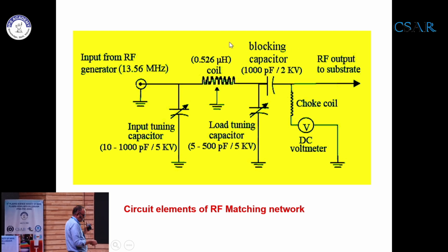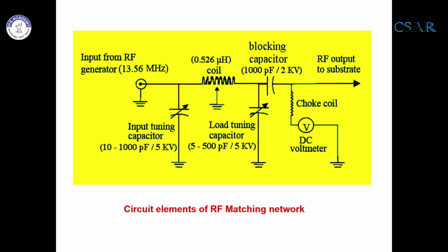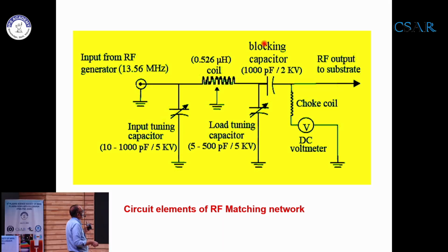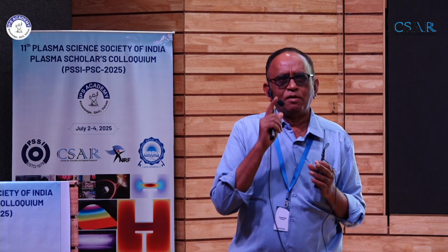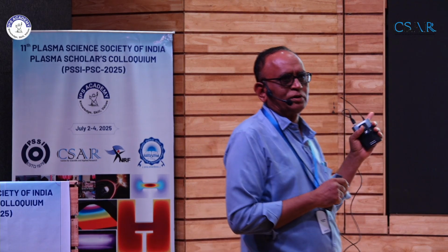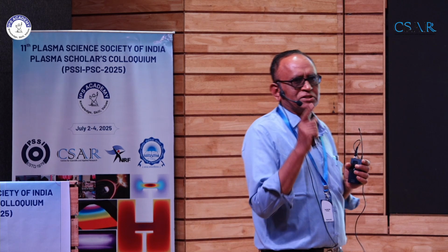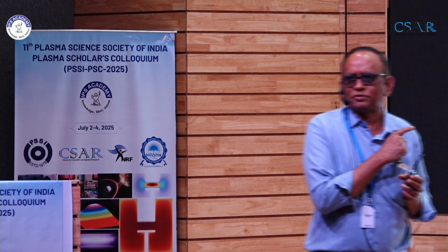Now the steady state charge will give rise to, again, this is electronics. See, here you have the negative charge that is accumulated, a steady state negative charge, and this steady state negative charge will give rise to a negative DC potential. So please remember, by incorporating that capacitor in between the RF generator and your load, you have generated a steady state negative potential on that capacitor plate.